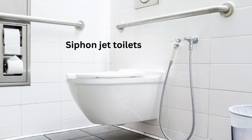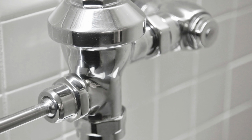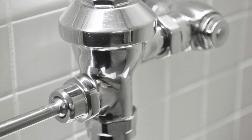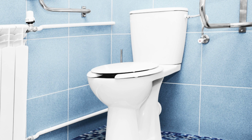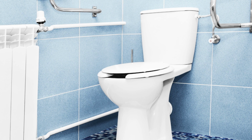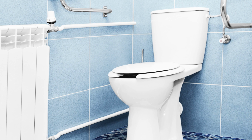At the same time, a jet located at the bottom of the toilet shoots a large volume of water into the bowl to create the siphon effect. The siphon effect occurs when the volume of water entering the bowl exceeds the volume of air that can escape through the drain. As a result, a vacuum is created that pulls waste from the bowl and sends it down the drain. The force of the siphon effect is powerful enough to clear the bowl of waste in a single flush, making siphon jet toilets a popular choice in commercial and high-traffic settings.